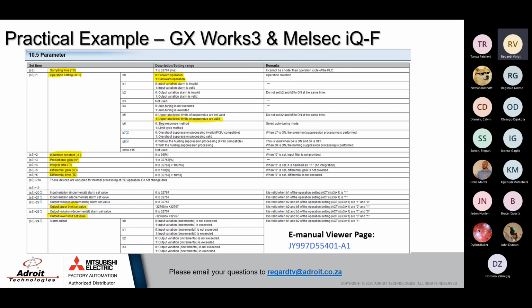There are a couple of them. The most popular one will be the Ziegler-Nichols method, which is used to do fine-tuning before the PLCs got intelligent enough to do their own auto-tuning. Okay, so the plants use that. If you don't want to go through all that method, because there's a lot of mathematics and calculations that you as a user need to perform,